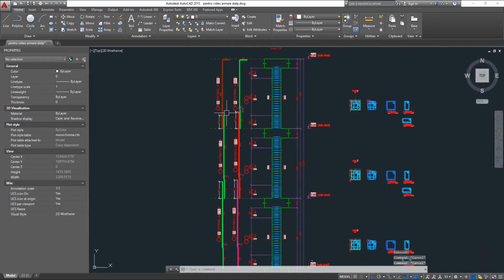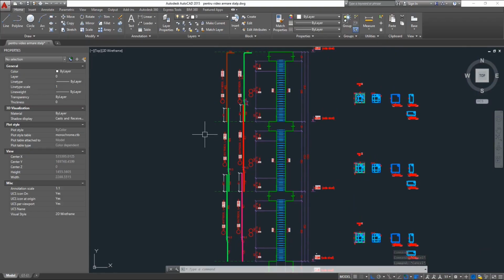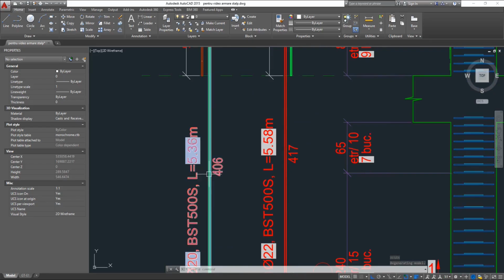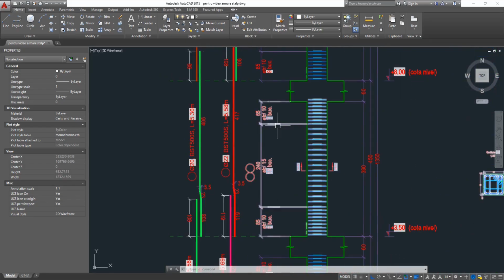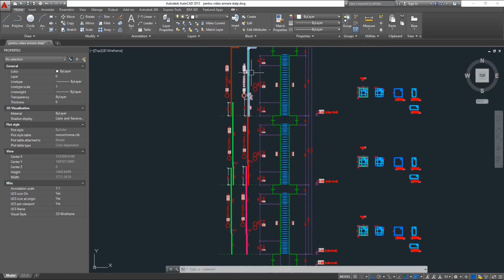And now we have the rebars fully armed on the elevation. We're going to regenerate, and the length of rebars will be adjusted, as well as the number of the stirrups on each level of the column. Now we want to take these rebars and place them on the body of concrete, if not for other things, at least for visual reasons, let's say.